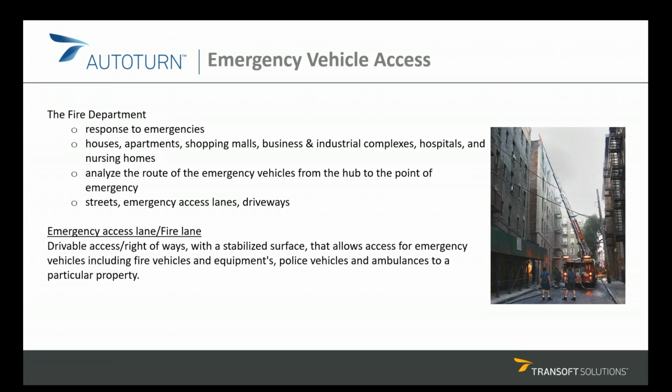So the emergency access lanes or fire lanes are drivable access with a stabilized surface that allows access for emergency vehicles, including fire vehicles, police vehicles, and ambulances, to a particular property. There are some design criteria that have to be followed while designing the streets as well as the fire lanes in order to be compliant with the requirements of the fire departments in the respective regions.